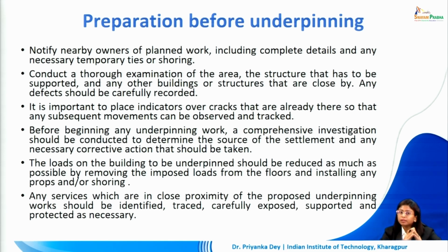Now we have to conduct a very thorough examination of the area, the structure that has to be supported, or any other buildings or structures that are close by that could possibly be impacted because of the fact that we are digging and making some changes in the foundation. Now, if there are any defects in any of these parts, we should definitely note it before starting the process. It is important to place indicators over cracks.